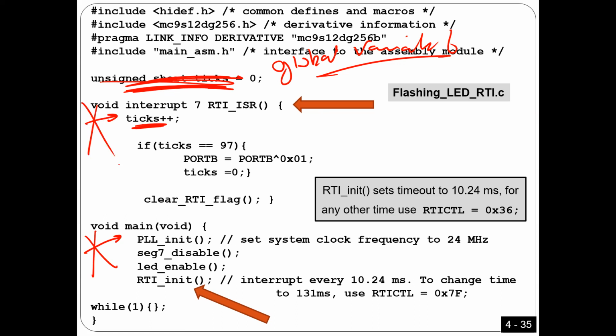Can anyone justify why, if I define this variable inside the interrupt subroutine, it is wrong? This is a common mistake. If I define it inside here, it's going to be a common mistake. It has to be a global. Yes. That's true. And also, if you initialize it in the main, then it would be a global variable, which means the interrupt function copy. That's true.